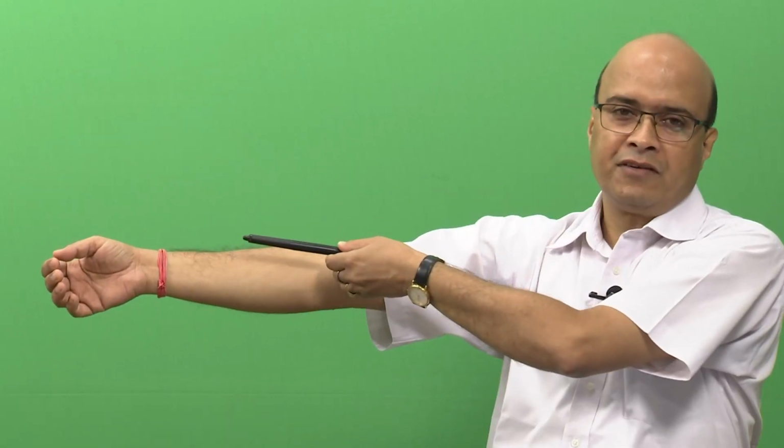Okay, this is the boundary singularity, and this shows that if I want to move in a straight line as I am going near there, it will be very difficult to control velocity in this direction. I can move in this direction very easily, but in this direction it will start becoming very, very difficult. Or it is one way of saying that the matrix is going to lose rank once you come very near a singular position.